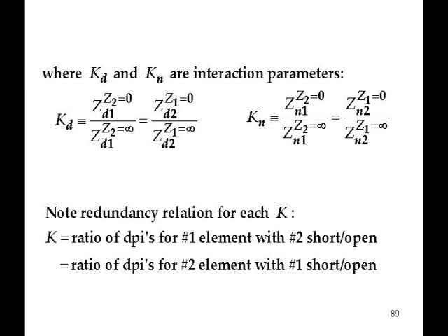And you can think physically how this works in a circuit. If there's a capacitor C2 near the output, and there's a capacitor C1 near the input before some interstages, then there's no interaction, because when you look in from one element, it doesn't care whether the other element is there or not, and vice versa.